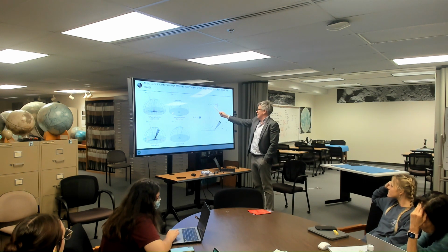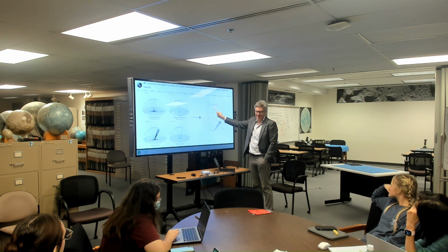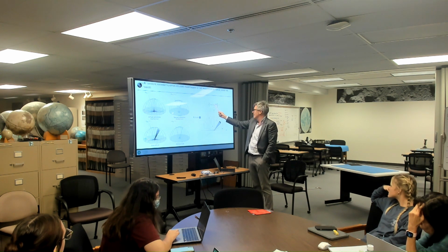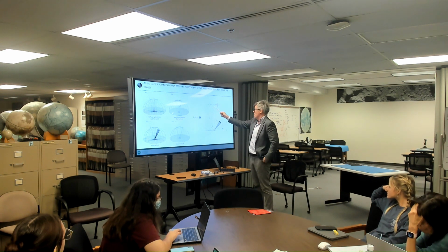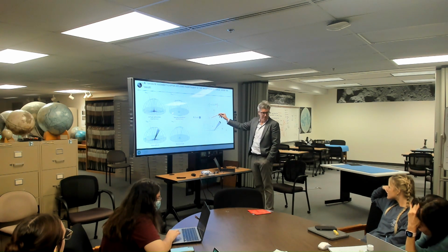Right? We've got to take the amount of energy that came in, multiply it by the transmission through the atmosphere, multiply that cosine angle, which is the angle of the sun, divide by pi, multiply by this, and we've got to correct for all these angles, the sun sensor angle.